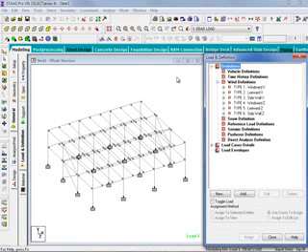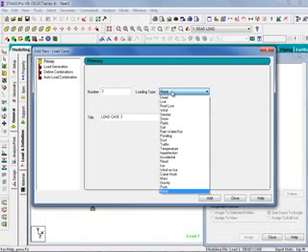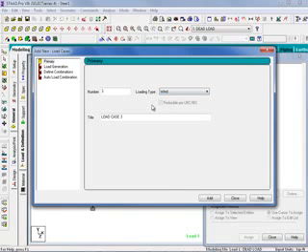We are now ready to create our wind load cases, which will then use those wind definitions to identify the wind pressures. We'll expand the Load Case Details group, highlight it, and then click Add to create our new wind load case. This is a primary load case. We will leave it set to number 3, and we will enter our loading type. The loading type will become important later on if you plan to incorporate this load into the automatic load combination generators available in STAAD.Pro. Of course, the loading type will instruct STAAD.Pro what load combinations to include this load case in, and also what factors to apply to it.